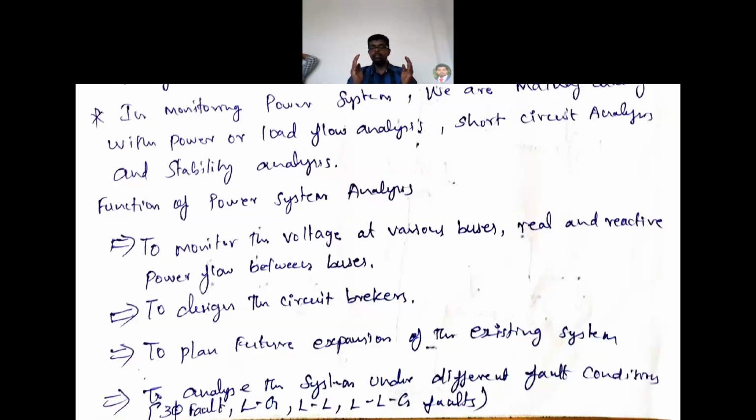Even for a substation, if they are planning, they will do like that only. If the load is 1 megawatt, they will consider the substation for 2 megawatt or 4 megawatt, because future extension is very easy. Instead of one feeder, they will keep 4 feeders. Instead of one or two transformers, which is more than enough, they will install 4 to 6 transformers, because sometimes a fault might happen, sometimes the load might increase. So you need to take one more feeder. Like that, it might be increasing.